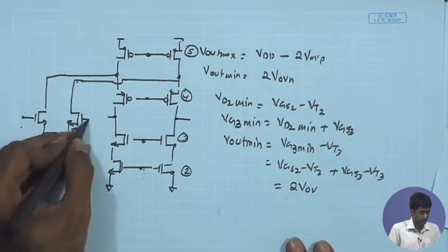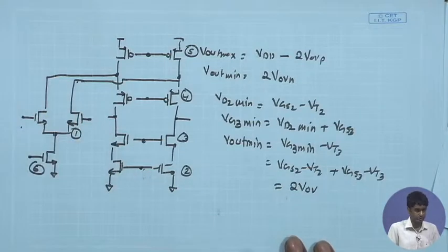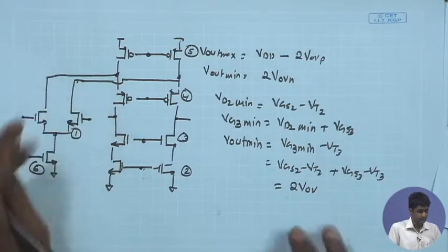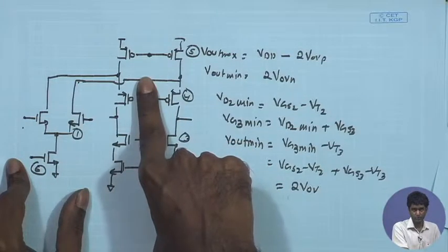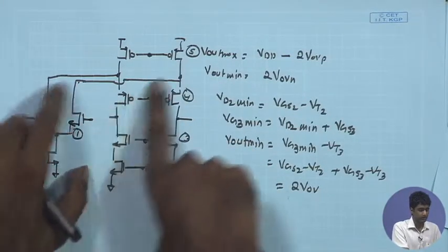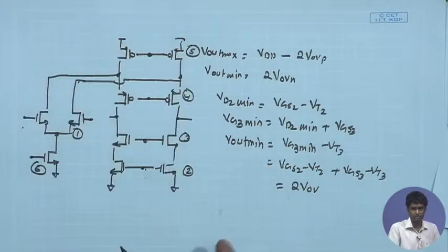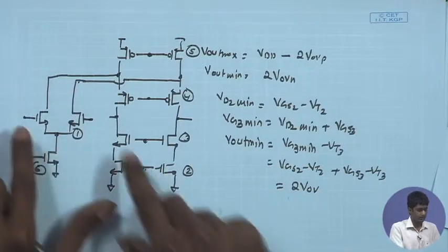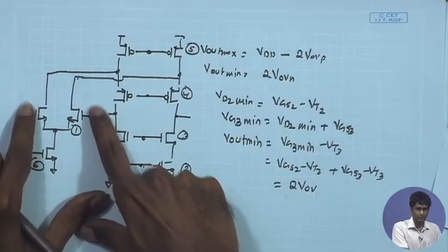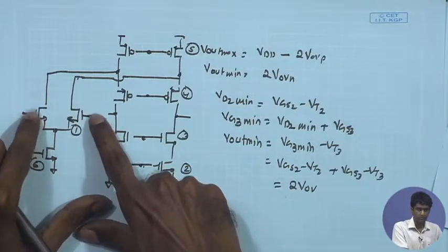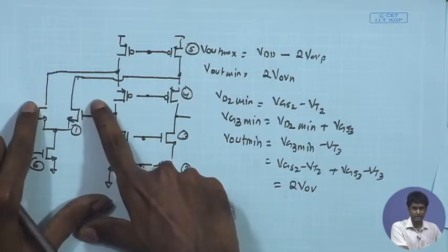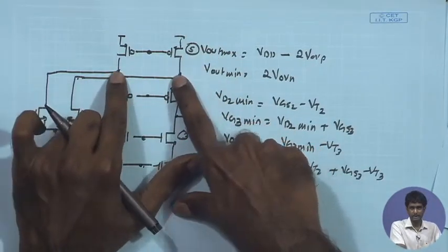And now we can also look at the input side. This is similar to our differential amplifier with current source load. So, you have an input pair, and the drain side is connected to PMOS, and therefore the limitation on the input common mode range is mitigated, because here the output DC point can be pretty high.